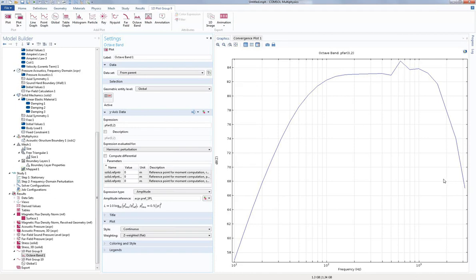How do you simulate different geometries of coils? For example, a double layer coil in-out or a coil former coil. Well, you typically add one coil domain for each layer of coil that you want to model. You can combine them in a number of fashions. You can model single-turn coils just as well as multi-turn coils. And in 3D, you have even more possibilities, of course, to model coils that are not perfectly round, but perhaps, I don't know, rectangular or have some other exotic shape.